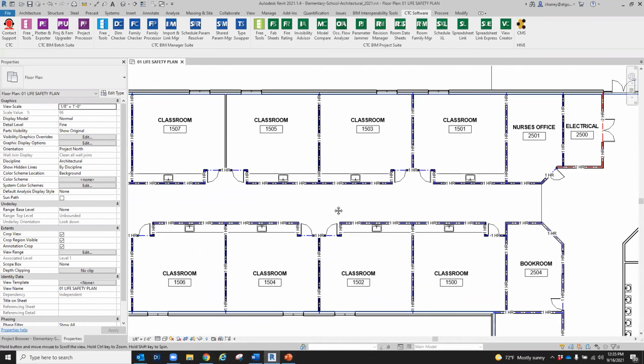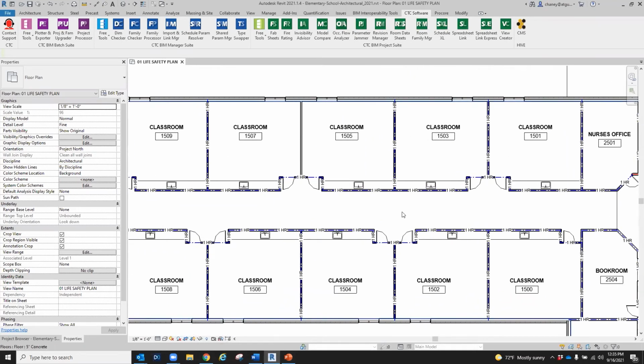And it's just as fast as the view template setting, which, like I mentioned before, you have the option with the tool to save out those mappings if you have multiple clients that you want to work with, or if you've got multiple reasons to have different line styles, different tags, things like that. Whereas if you were to go with the view filter and the view template route, you would still have to make a single view template, project template per style that you want.